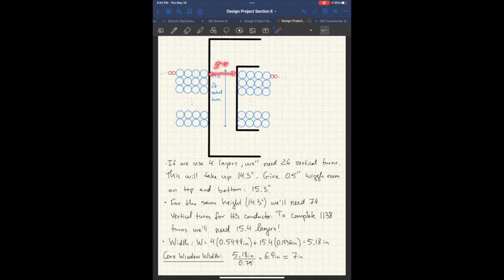What are we adding to that? 8 diameters, because we have to add 4 diameters, plus another 4. This is the distance that's no longer changing, the constant distance. So instead of 5 inches, it's going to be 5 inches plus 8 diameters of the low side conductor. Following or no following? Okay, cool. So that's going to be the constant number.